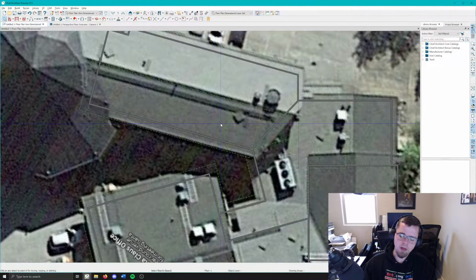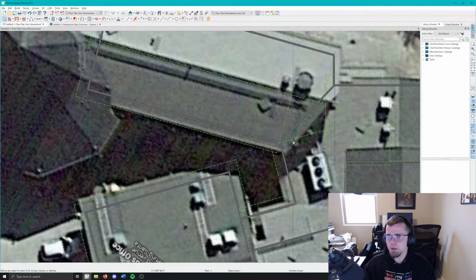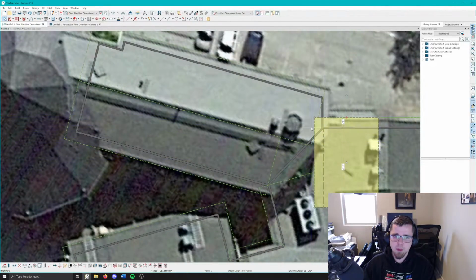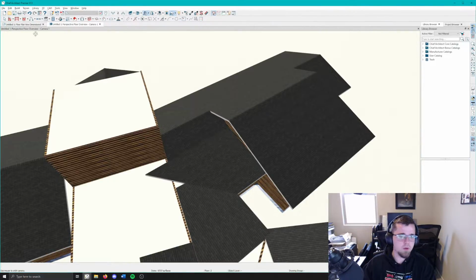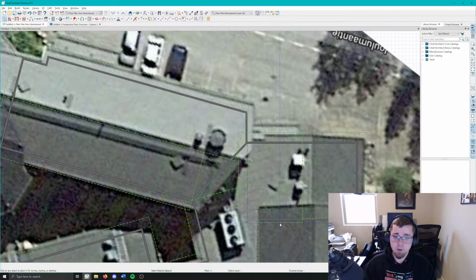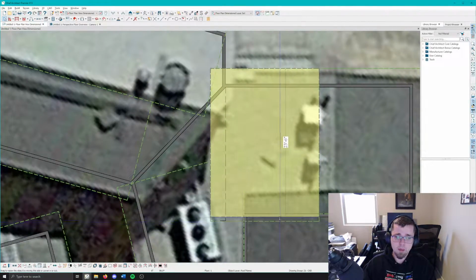Your house doesn't have to be a big rectangle with just a gable roof over the top. But I do recommend keeping it as simple as possible without compromising the design. This type of complexity becomes expensive. At the end of the day, put yourself in the worker's shoes, in the framer's shoes. If you were up on top of that roof, you don't want to be on a real steep pitch.